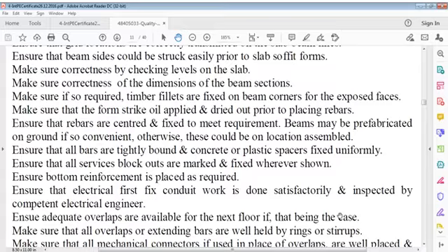So 25 or 20 mm triangular fillets must be placed, plastic fillets or whatever else. Don't use timber for that, it takes time. Use plastic fillets, the triangular ones are available and you can buy them. Then apply form oil like earlier, but you have to apply it carefully. It has to dry out before the concrete works, or before the steel works.